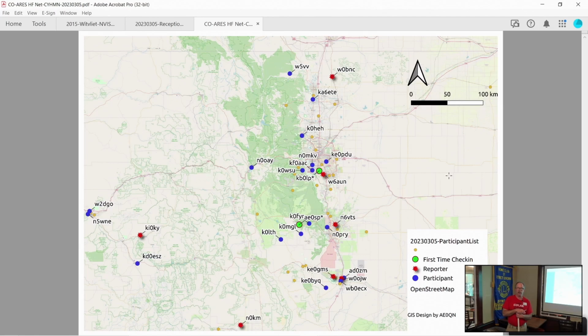If you're in the desert or a big open prairie, like Pawnee National Grassland, there's not a lot of trees out there. So if you don't have supports, poles or masts or fiberglass masts or PVC or something, you might have to run something from the top of your car out to a rock or something like that. So do what you can, but dipoles work quite well.